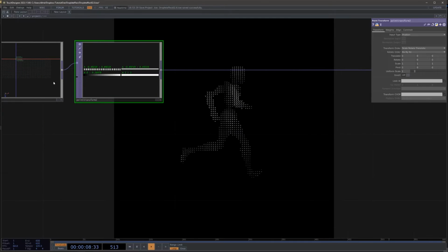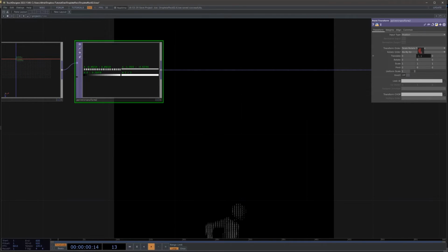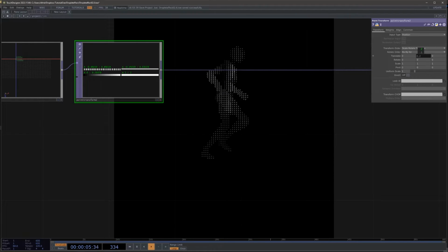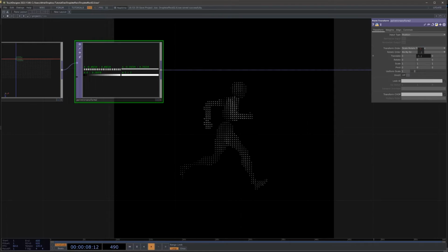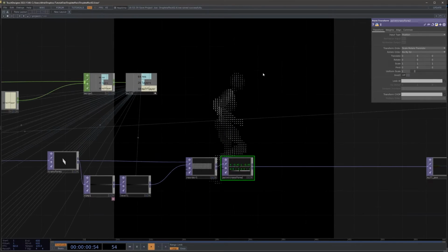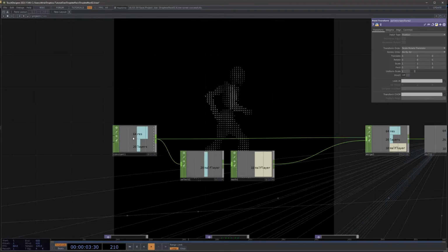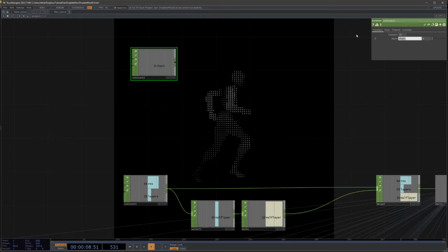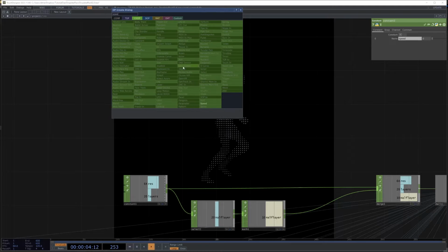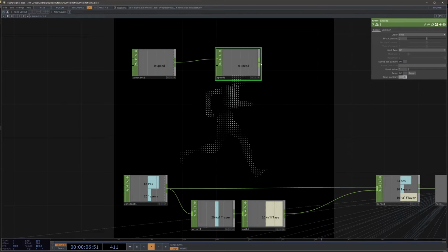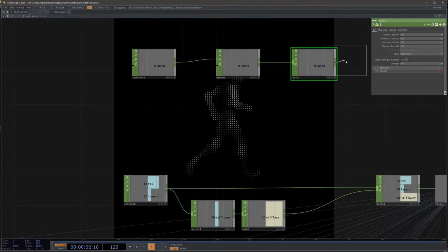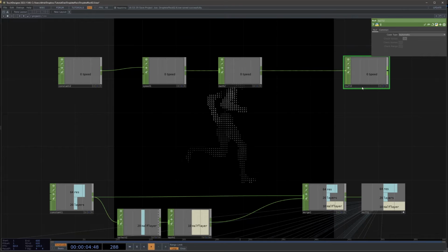And this point transform, I'm going to offset it in order so it falls. To do so, I could either add an expression like uptime.seconds minus uptime.seconds, but I want to have control over the speed of it, so I'm going to add a constant, and I'm going to call it speed, and link it to a speed, and then to a mat, and then to a null, and this null will be called null speed.